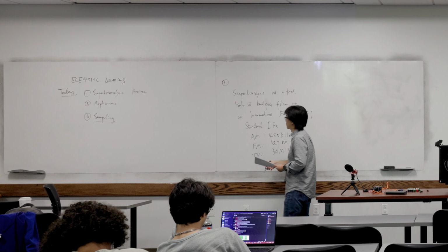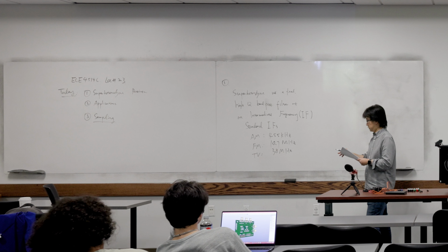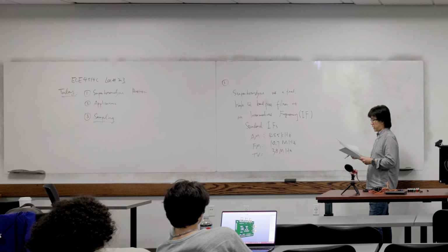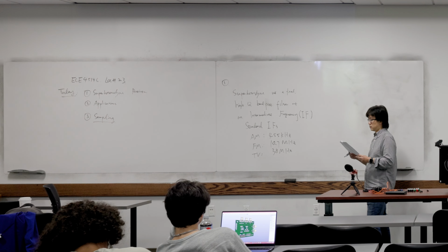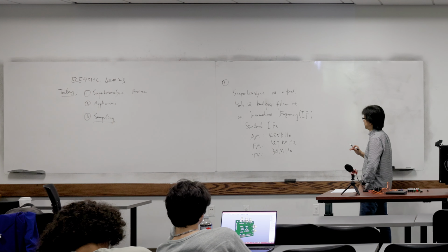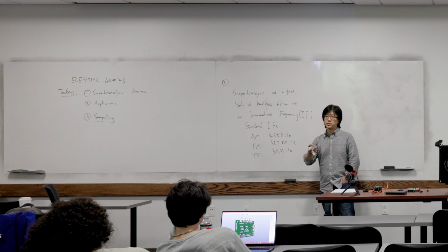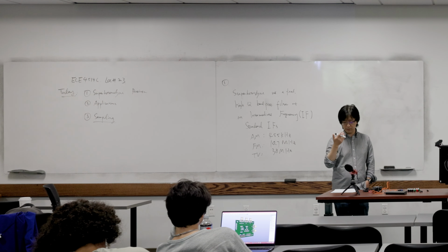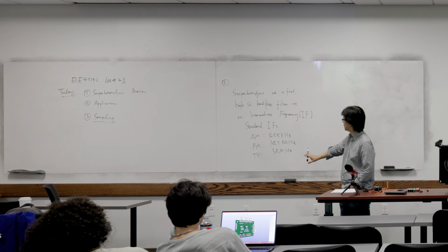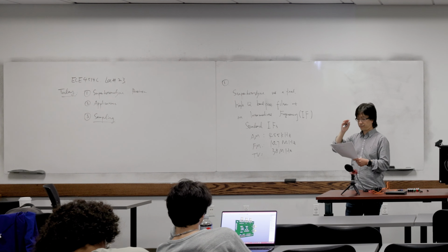Those are the typical frequency range for the intermediate frequency. So basically we design a high quality filter around this point, and when we receive the signal, we shift the signal to exactly this frequency, and then filter the signal out.